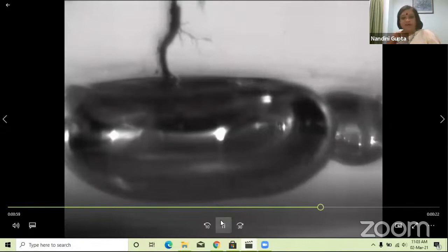Yeah, so this is a very nice video that I like to show in my lectures on PD, because here we actually see a filamentary tree channel supporting PD activity, and the PD activity causes stress mechanisms to degrade the insulation around it, and a very thick tree channel is caused.